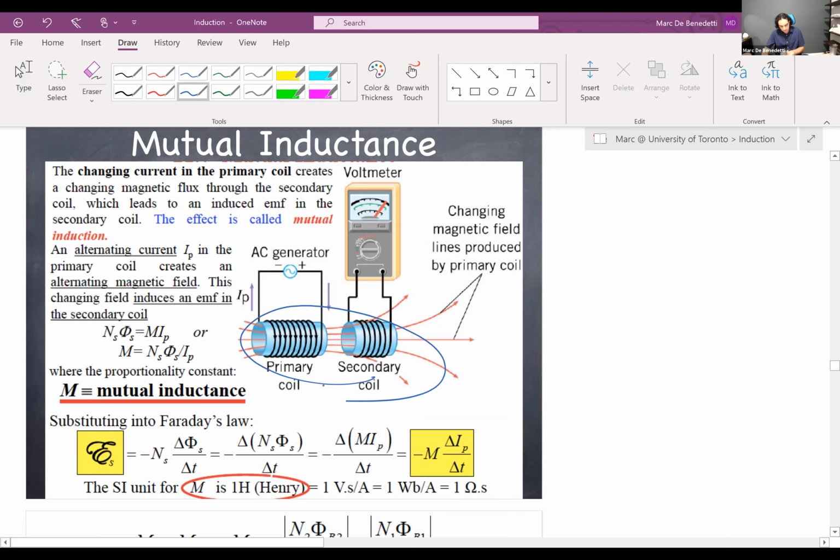So something like this, for instance, there's no iron core. You see here that some of the field lines are missing the coil. So it's not a perfect transmission. It's an imperfect transmission. So if we're talking about a transformer and there's an equality there, the equation is super easy, right? Because there's an equality, we can just get the transformer equation. If there is not an equality there, then it becomes hand-wavy. Then it becomes, well, look, we have to come up with a number, M, that quantifies the ability the two coils have to quote unquote talk to each other, feel each other's presence.